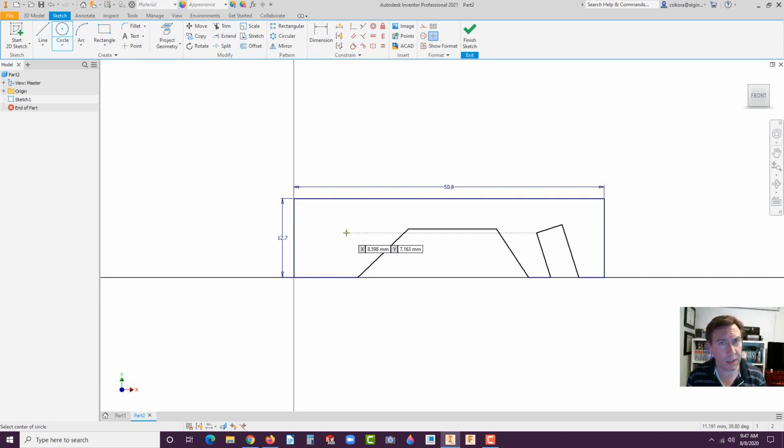But anyhow, when it comes to that geometry, mathematically behind the scenes, it calculates what are called nodes, or the elements, which are the corners of each one of those polygons. And as a whole, it can calculate where the highest amount of stress is going to occur, and whether or not, depending upon the material information you put in, it's going to be a valid design. If it's going to be too weak and possibly break or fail, and or if it's going to be over-engineered.